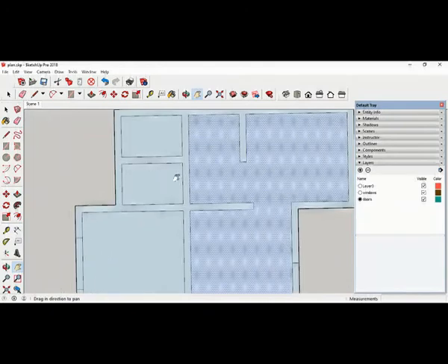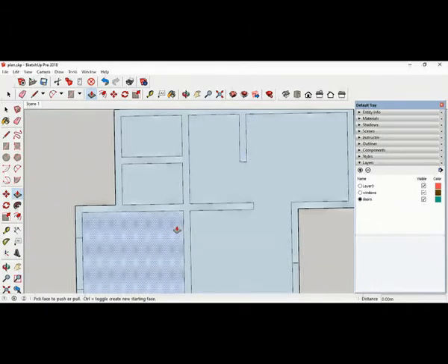So here also you have to draw, so the toilet is coming from here. Tape measure tool, 0.1, 0.75, rectangle, erase, just type E, shortcut you have to learn, no need of pressing enter or anything. So this right here, and there is one door here.